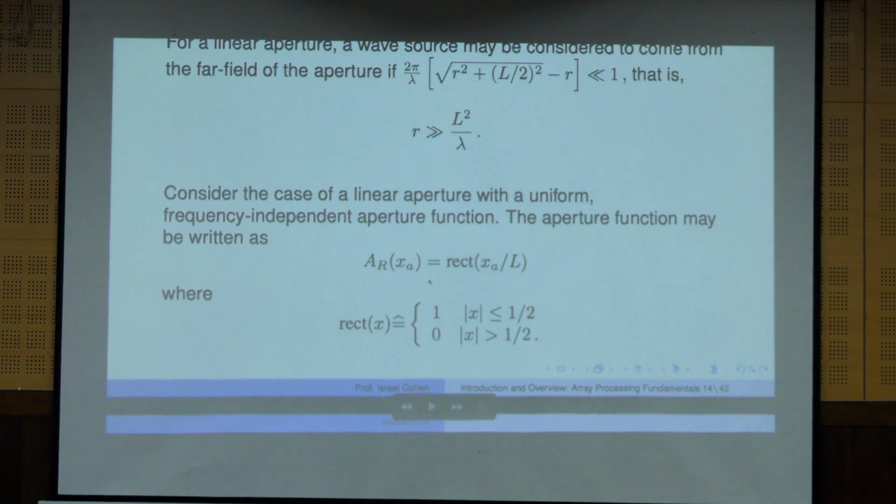Okay, so far, the objective with this simple example is just to show the directivity of the aperture, which means that the electrical signal that is measured by the aperture in response to an acoustic wave with a certain frequency depends on the direction of the signal. And this is very important because it means that we have different responses to those signals that come from different directions,